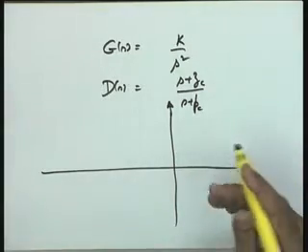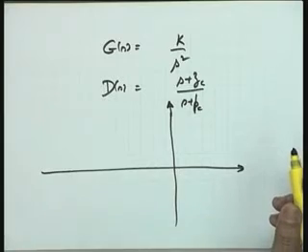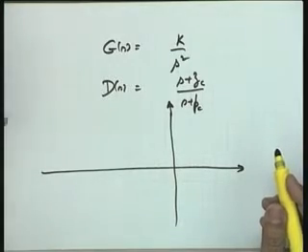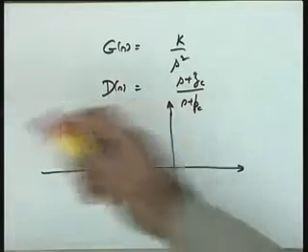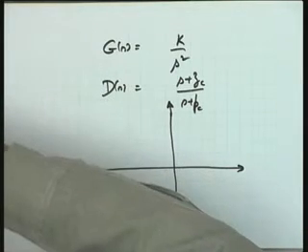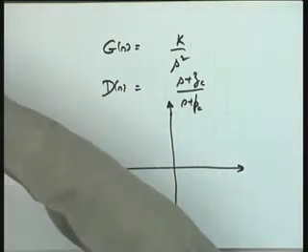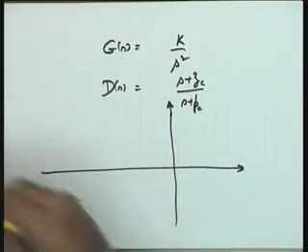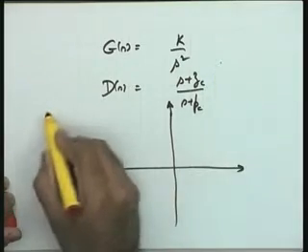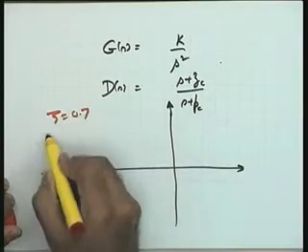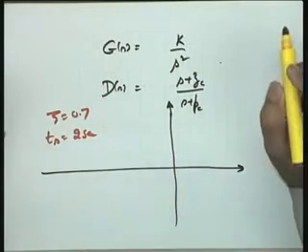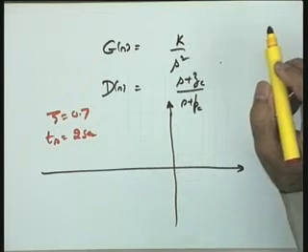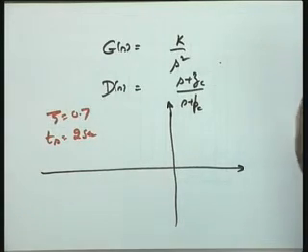The concept is this, that I want to pull this particular root locus to the left so that the transient performance requirements are satisfied. So first of all I will have to look at the transient performance requirements, and let us say that the problem under consideration demands zeta equal to 0.7 and settling time equal to 2 seconds. These are the performance requirements the user has given you. You have to meet these requirements. So from here the design procedure starts.